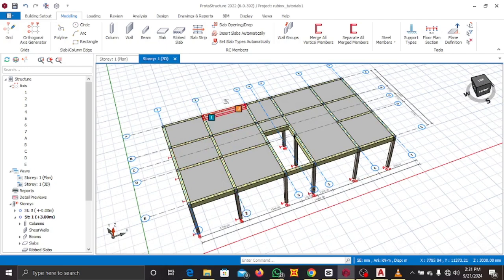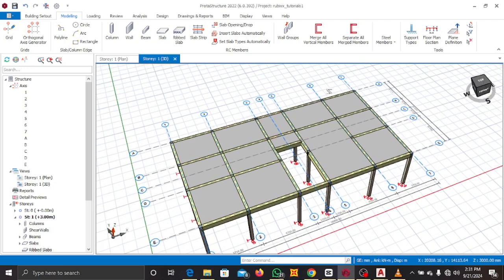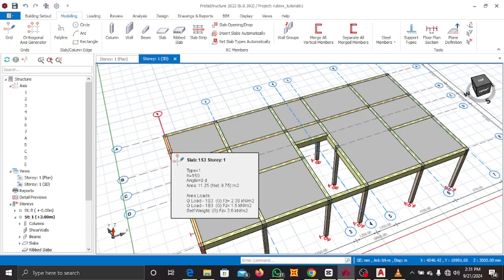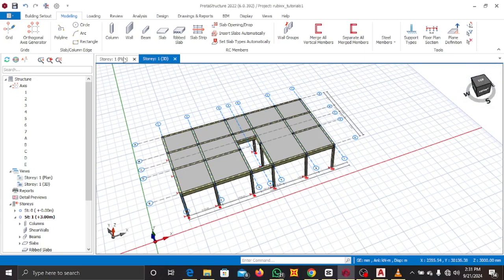It's also important that as you are designing and inputting this, you're also checking the architectural drawing to make sure that wherever you place your column corresponds to what the architect proposes, so you don't end up placing columns or beams where you're not meant to, and also to know where to place slabs and where you have cantilevers. Okay, we can come back to our plan.